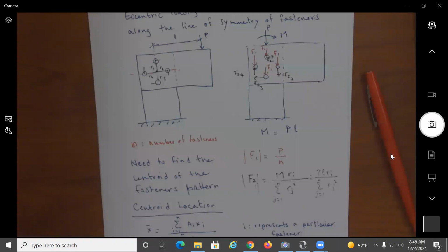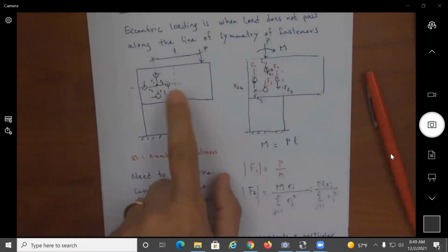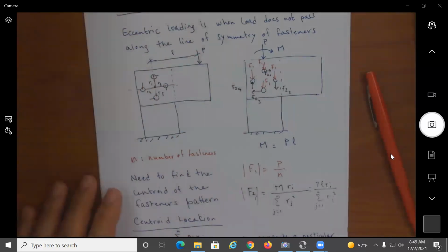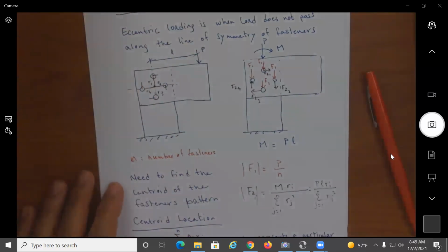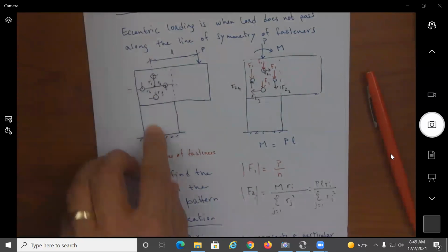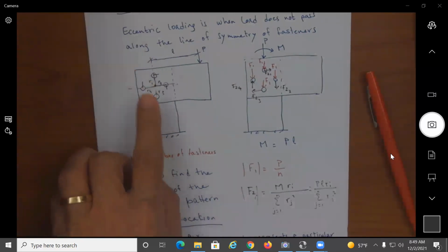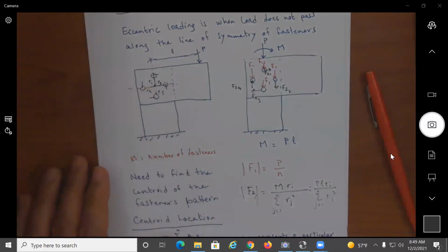Then we can start looking at the shear of the fastener, at bearing, and at the tear out. We also want to check the member. A member like this is subject to a bending moment, and I should look at the critical section that has the most holes, calculate an equivalent moment of inertia, and find the stress.